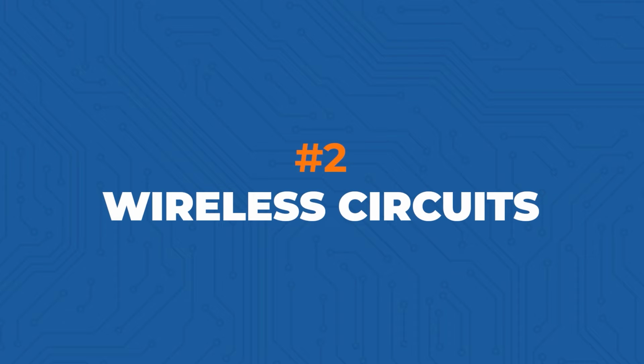But for most other circuits that will perhaps use a module, the main area that may be complex is wiring up the feed line to an antenna. If you use a module that has a built-in antenna, this isn't an issue. But if you use a module that requires an external antenna, and by external, I don't necessarily mean external to the product. I mean external to the module. It could be an antenna that's visible on the outside of the product, or it could just be an antenna that's mounted on your PCB board, but not on the module itself.